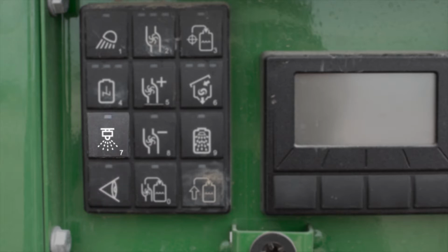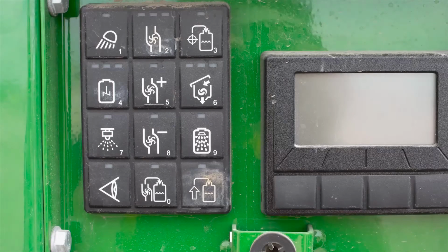Along the same line too, Matt, if we look at the number 7 button just above the eye, if we wanted to turn the whole boom on all at the same time, so say I cleaned out my boom strainers or I was rinsing the machine, I can turn the whole machine on at once too, and it'll run at basically a minimum pressure and allow us to do that from the ground without having to hop up into the cab, punch in a simulated speed, for instance, turn on the pump, turn on the master. I can do it all from the ground by turning on my pump, hitting my number 7 or the visual check button in the lower left, and make all the checks we need without going anywhere except by the ground. So I got all my tools and everything with me. I don't have to contaminate my cab with working on the nozzles and keeping the cab clean.